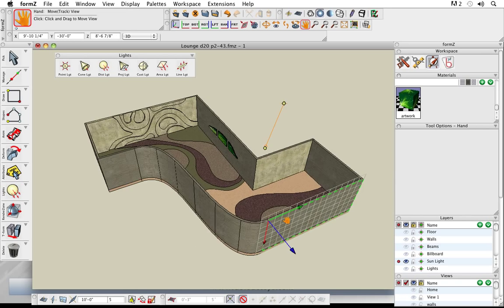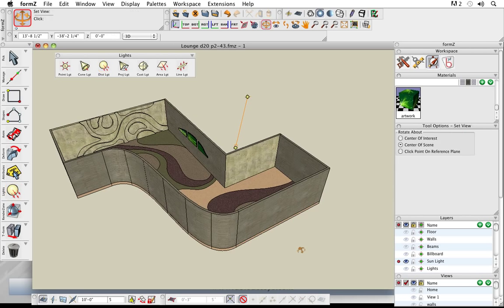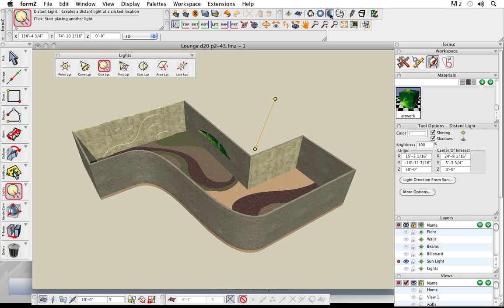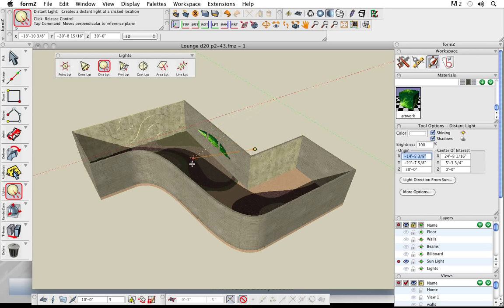And this is great when you're just originally conceptualizing and building the different parts of your model. But if you want to see the actual effect of the lighting in the scene, then of course we need to switch to this next mode, which is shaded full. So I click on that, and now you can see if I were to move that light source, it is actually live, interactively using the actual light sources themselves. So we get the shadow effects.